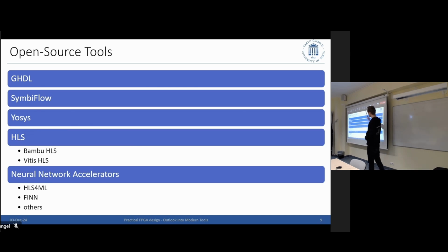Just to go through the tools, GHDL might be very nice for you to use if you do not want to go into synthesis or just want to learn a bit of VHDL. I used GHDL in my course where I learned VHDL coding itself. However, whatever can be simulated in GHDL may not be synthesizable. It's not a complete tool, if I understand correctly.